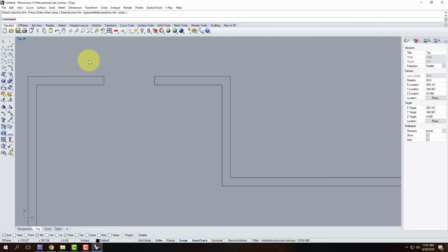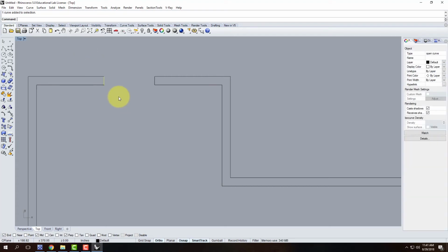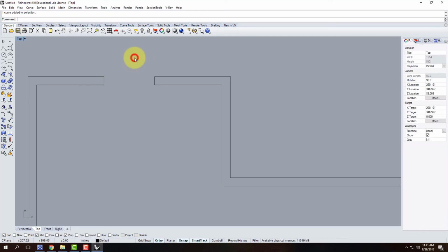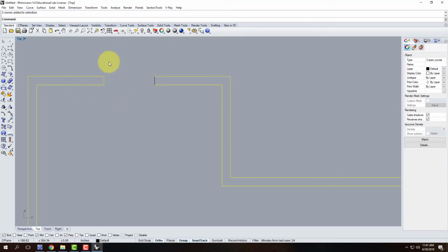If you select from the left to the right, it will select anything completely contained within your selection rectangle. So I'm starting at the left side and going this direction. The only thing that will be selected when I let go is that line. If, however, I start at the right and go toward the left, and select the same rectangle, it will select everything that the selection touches.